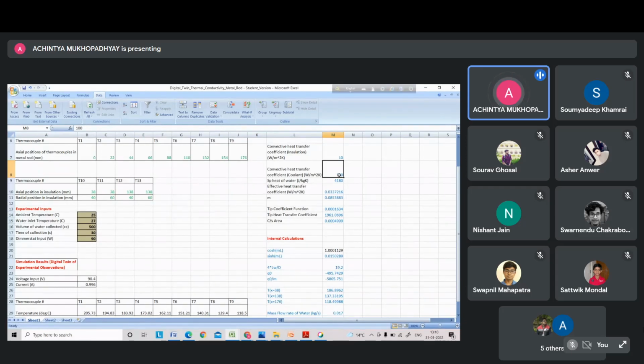100. Similarly, for the radial heat loss from the fin, there are two resistances, as I said: the conduction resistance through the insulation and the convective resistance at the outer face of the insulation. Using these two series resistances, I derived an equivalent resistance in terms of some effective thermal conductivity. Do you understand this? Instead of these two resistances, I put an effective convective heat transfer resistance.